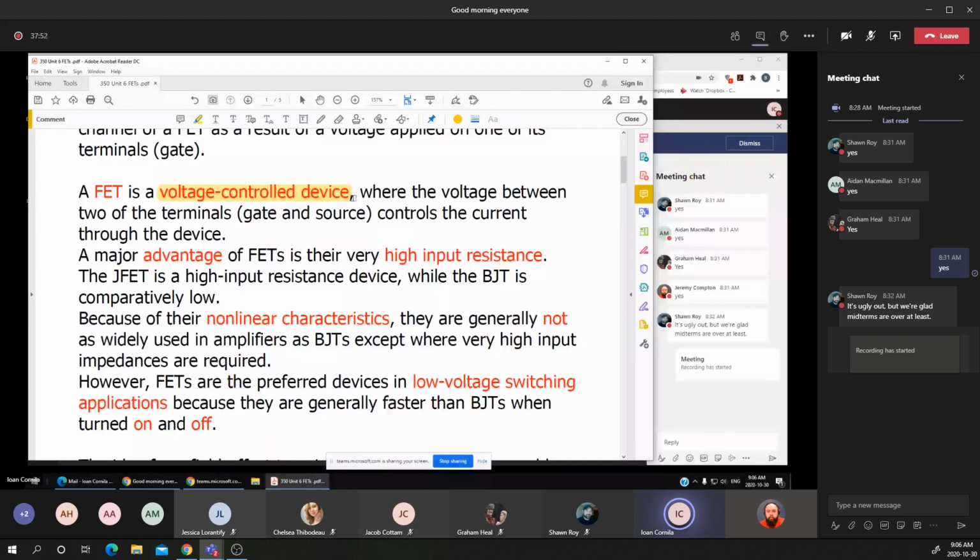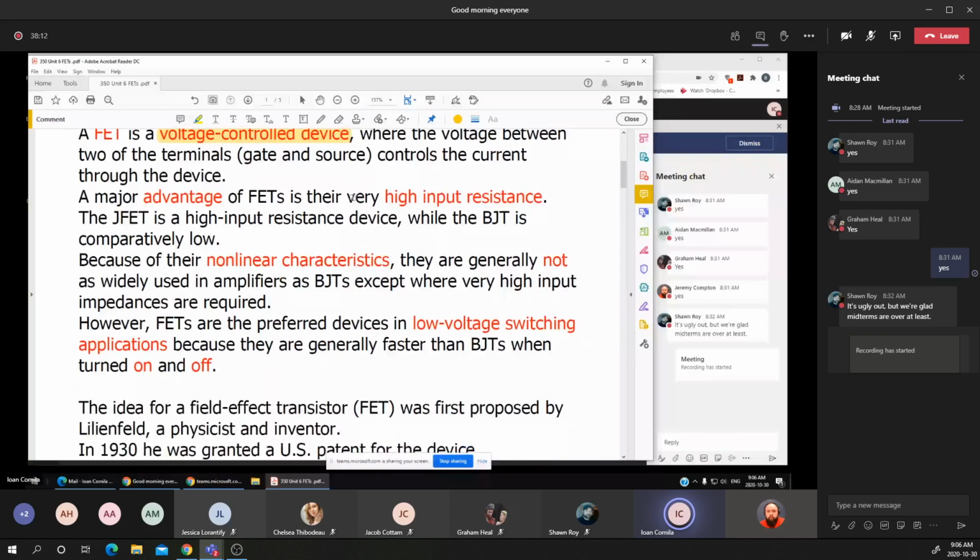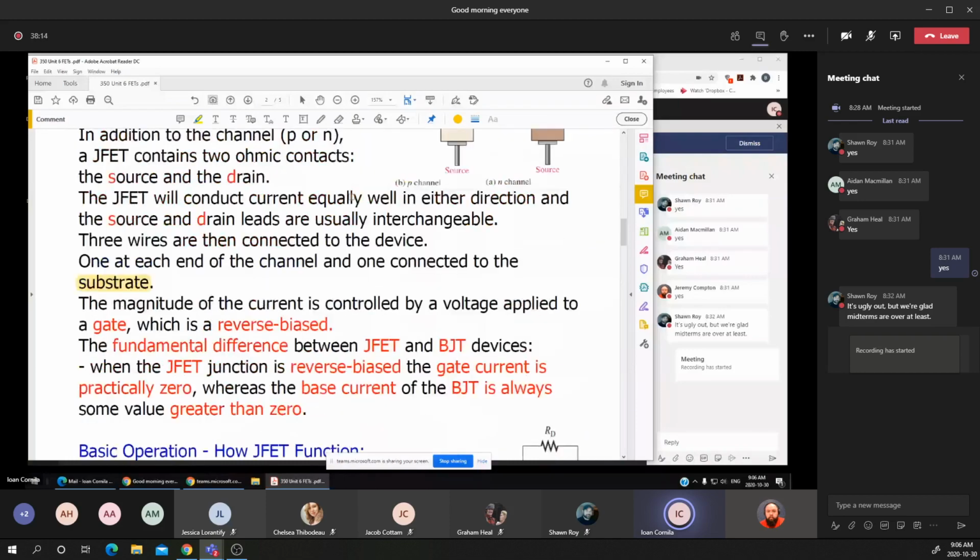Without applying a voltage to the semiconductor, we actually can destroy the semiconductor or the FET transistor or the integrated circuit. That's why it's a special precaution, how we can handle and how we can use those FET devices.